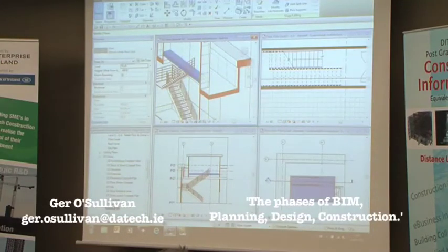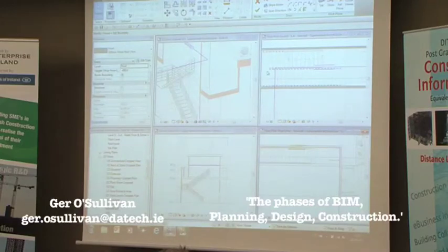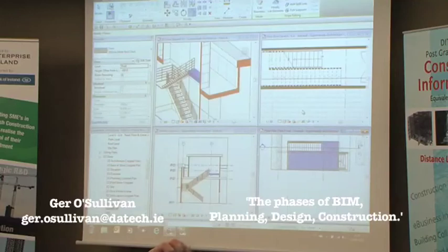So we can select the floor afterwards, edit it, and then say on this plan, because it makes a bit more sense to do it on the plan where I can see the stair, we can then begin to pick the edge of it, lock it in. Again, a feature of Revit, pick the edge of that wall if you wanted to, lock it in. Why would I do that? Well, if the wall moves or if the stair moves, they will update. And that's what we like to see happen. We don't want to have to go around and edit things that we would like to edit automatically. So that's now the new shape of the floor with the opening cut in it. We'll finish the floor, and we now have the floor with the opening that we need.